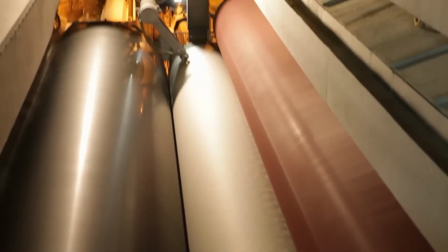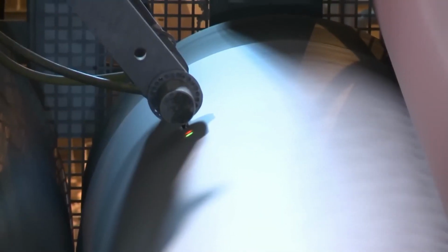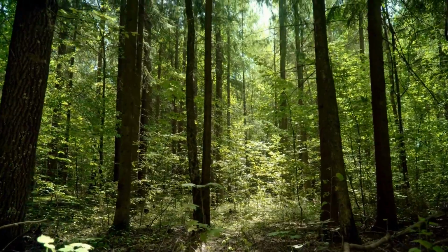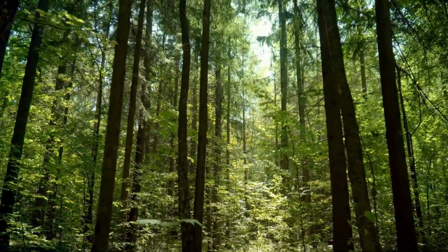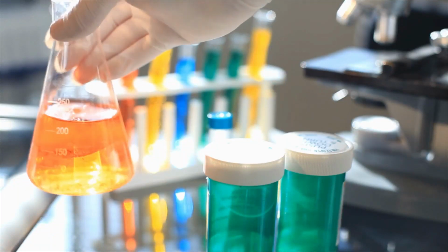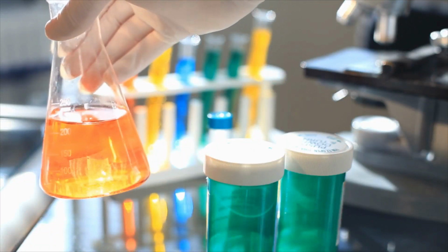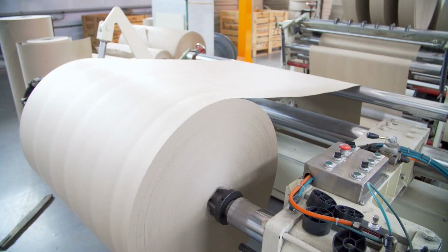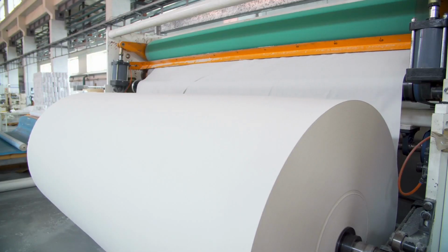The finished paper is then wrapped around a hairdryer and then wrinkled, giving it that typical softness and slightly wrinkled appearance, before being made into rolls of toilet paper in a dedicated machine. Paper companies often maintain their own plots of trees to ensure the quality of the finished product, while also carefully monitoring the chemicals used in the pulp production process. The paper produced is tested for several characteristics such as elasticity, opacity, moisture content, smoothness, and color.